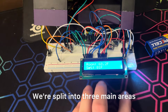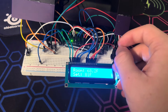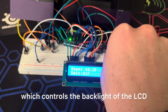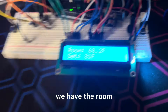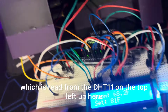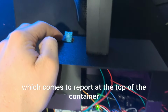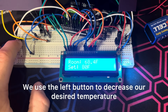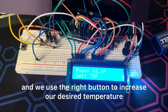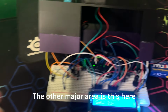We're split into 3 main areas. This is the LCD component. It has a potentiometer here, which controls the backlight of the LCD, changing visibility for the user. As you can see here, we have the room. This is the ambient temperature room, which is read from the DHT11 on the top left up here, which comes through a port at the top of the container. The set is the desired temperature of the user. We use the left button to decrease our desired temperature, and we use the right button to increase our desired temperature.